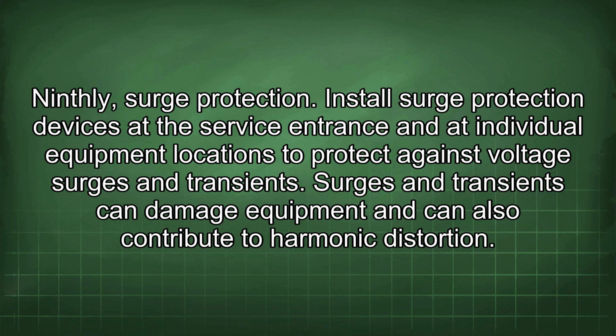Install surge protection devices at the service entrance and at individual equipment locations to protect against voltage surges and transients. Surges and transients can damage equipment and can also contribute to harmonic distortion.